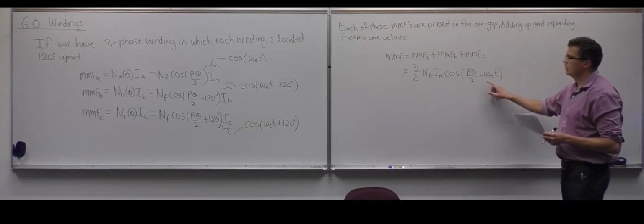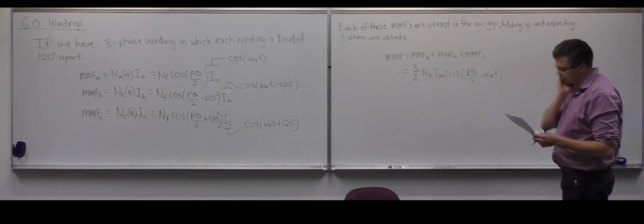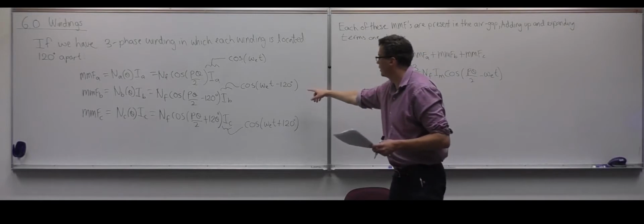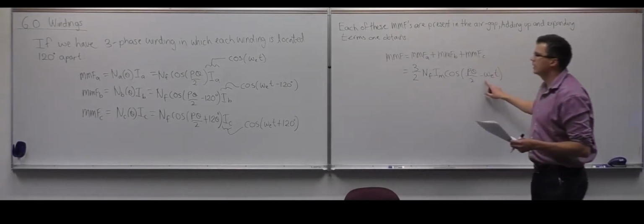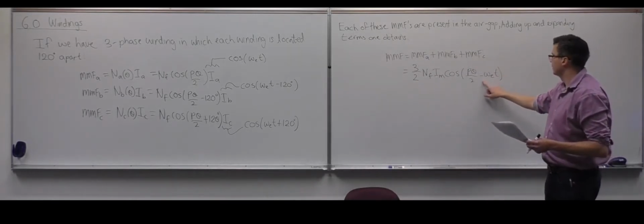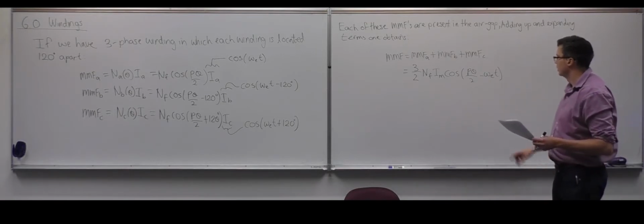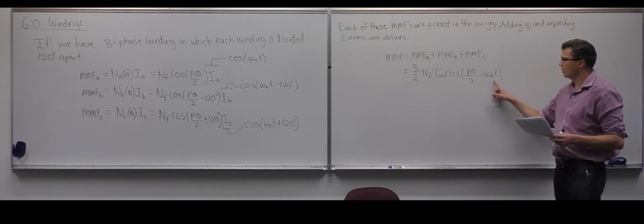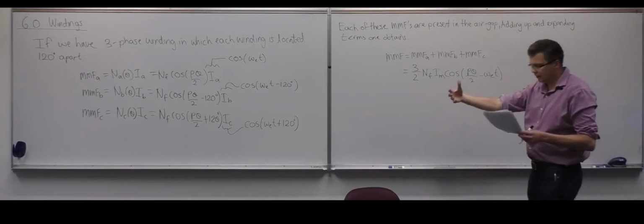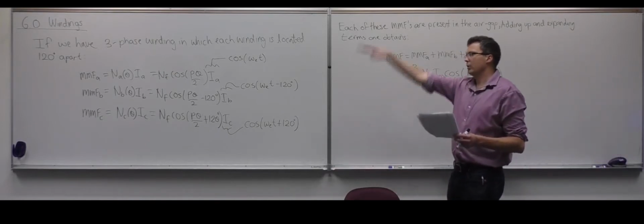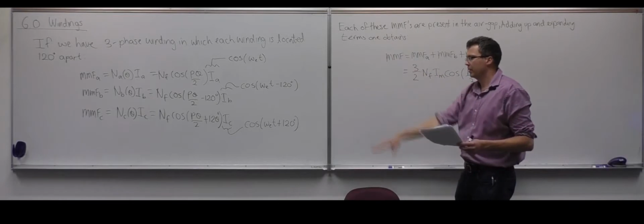This is different to the other terms in here, because it's creating a traveling field. If you recall from your electromagnetics with wave propagation, this results in the field traveling around the air gap as time goes by, whereas these fields are just going up and down in magnitude, but they're not traveling.